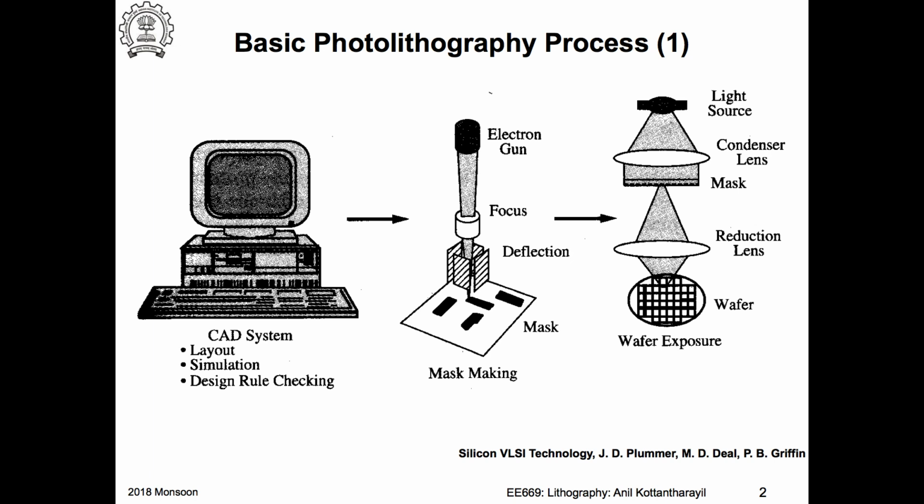A plastic sheet, maybe a millimeter or so thick, and you can print on the transparency sheet using your normal printers. If the feature size is more than 20 micrometers, you can get these features printed on a transparency sheet. You don't have to go and buy glass with chrome coated on it, which is very expensive.